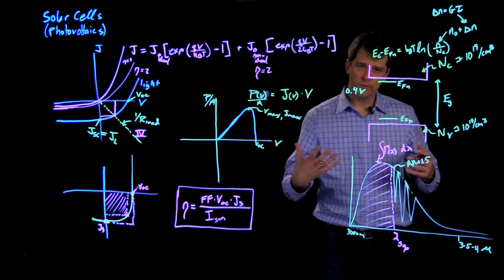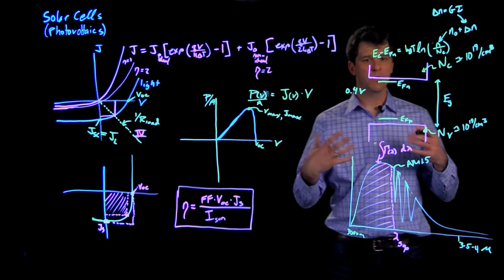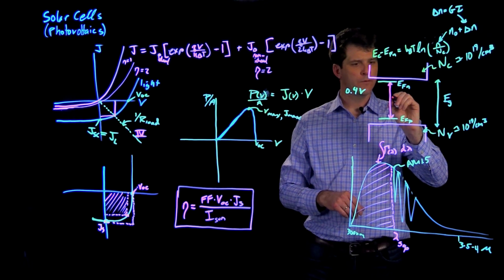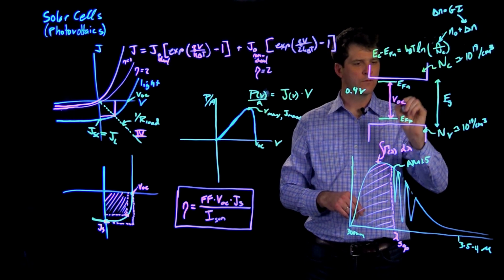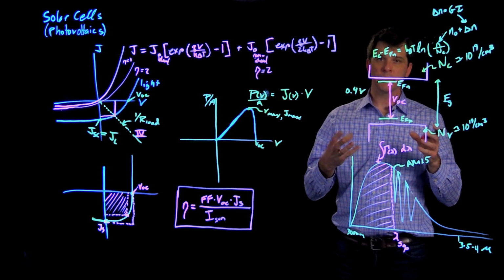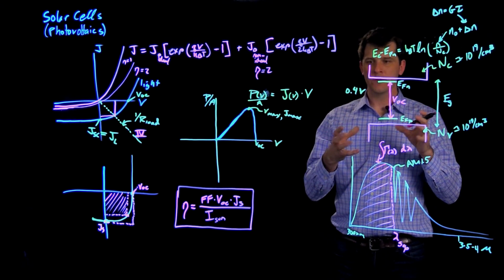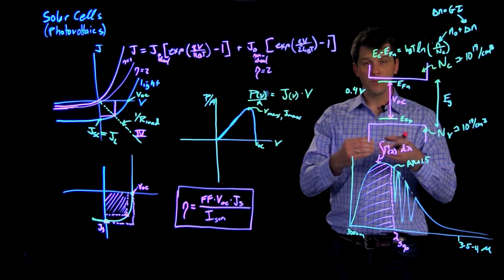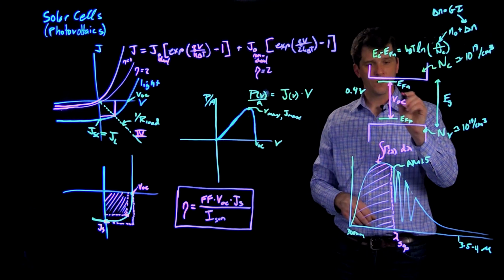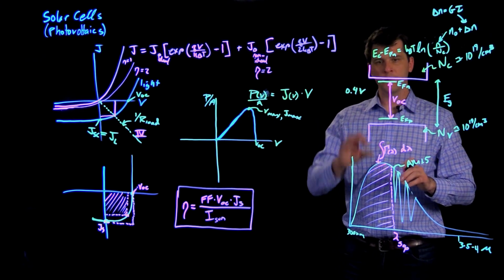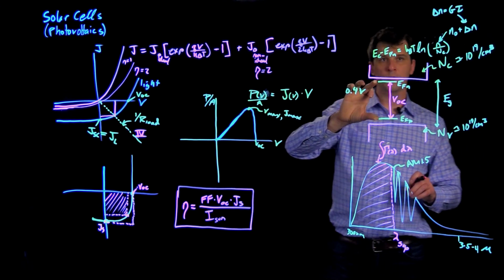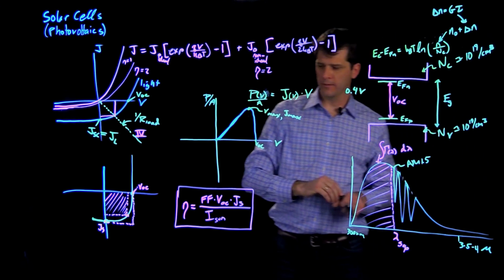Now, the quasi-Fermi levels represent the chemical potentials for electrons and holes, and so we can figure out finally that the maximum voltage that can ever be stored inside the semiconductor by steady state excess hole concentrations can be measured from VOC, and that's literally the quasi-Fermi level splitting for electrons and holes under the conditions of light illumination.